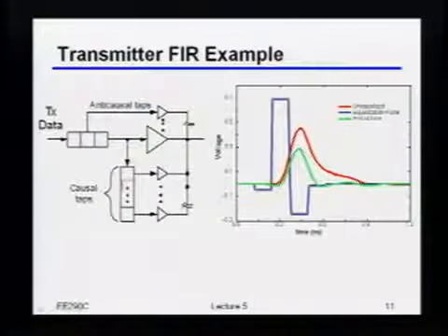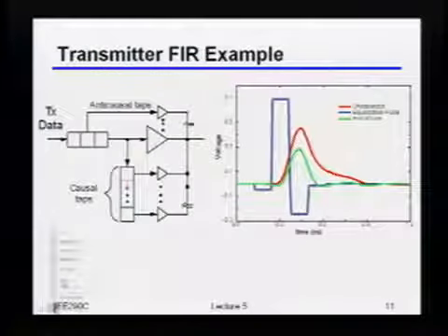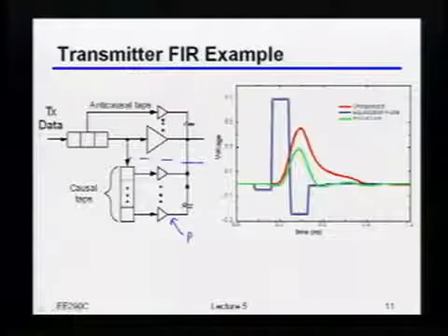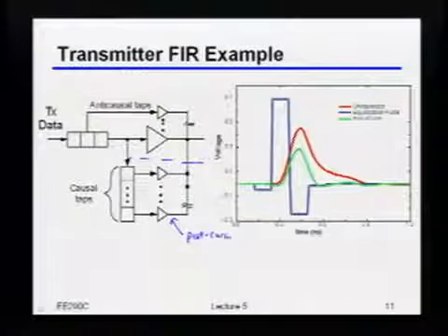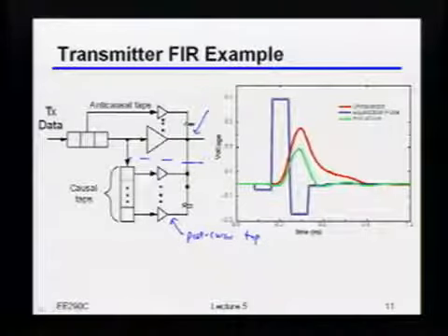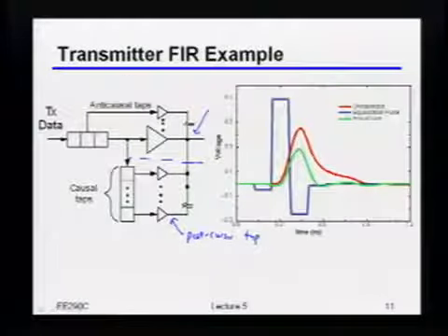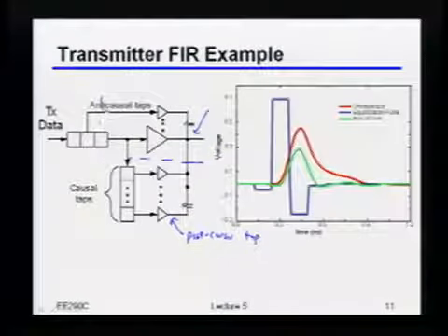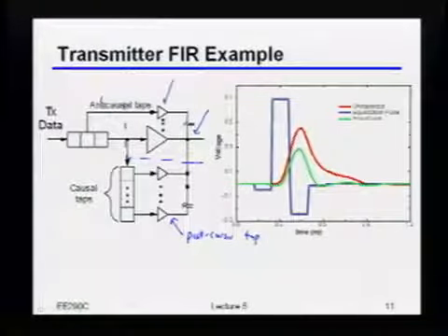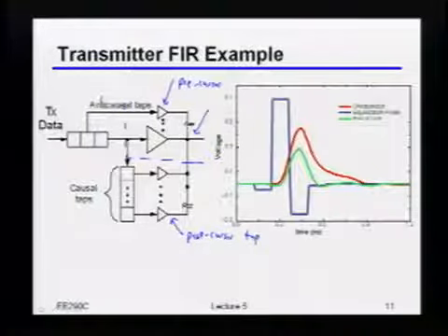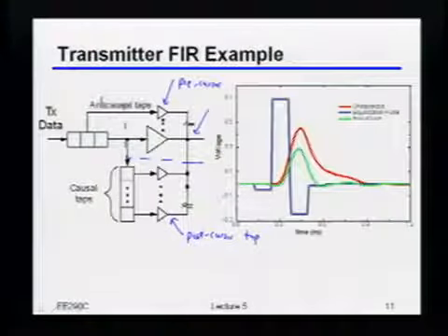These things would be trying to equalize the response of the channel. Just from a terminology standpoint, all of the stuff down here, meaning after that big guy, is what's called a post-cursor tap. Cursor just means your main, largest amplitude. That's the actual bit that you're trying to send. Everything that's before that, for example that guy, is called a precursor. So pre and post just refer to relative to the biggest amplitude that you have.